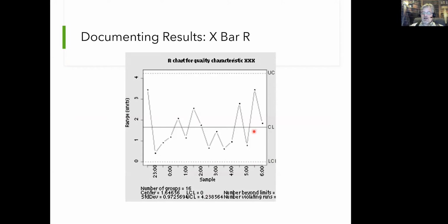And typically you would document your measurement on a chart like this so that you can visually see how you're doing. If you start to see that part trend down, you get shorter and shorter and shorter, you may stop what you're doing and check everything in the manufacturing process, because you don't want that to trend down below your lower limit. And now you have to start throwing away parts. So you're measuring these parts and wow, that part's getting shorter and shorter. Stop, let's figure this out, and then restart the process.